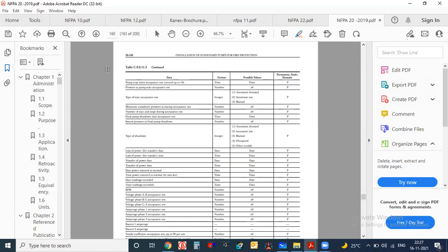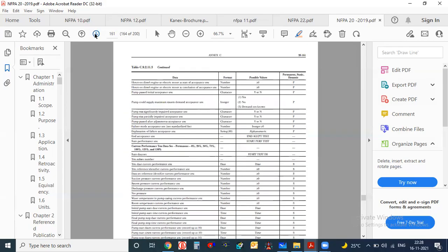But I heard from one expert that it is better to assemble at site only, because sometimes when you assemble and bring from the factory, the test pressure will not come. So it's better to test there itself, and if any accessory is not good, it can be replaced after seeing that. The installation of a firefighting pump, not only firefighting pump, take anything, whether plumbing or HVAC pumps, will almost take 1 to 2 weeks, and it is a separate cost.